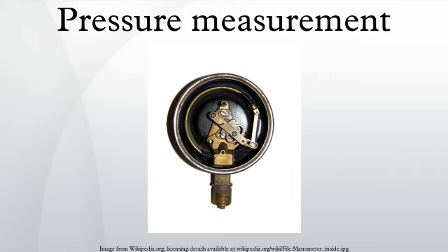If the process pressure connection of an absolute pressure transmitter is open to the air, it will read the actual barometric pressure. Units. The SI unit for pressure is the Pascal, equal to 1 Newton per square meter. This special name for the unit was added in 1971. Before that, pressure in SI was expressed in units such as N/m². When indicated, the zero reference is stated in parentheses following the unit, for example 101 kilopascals (abs).